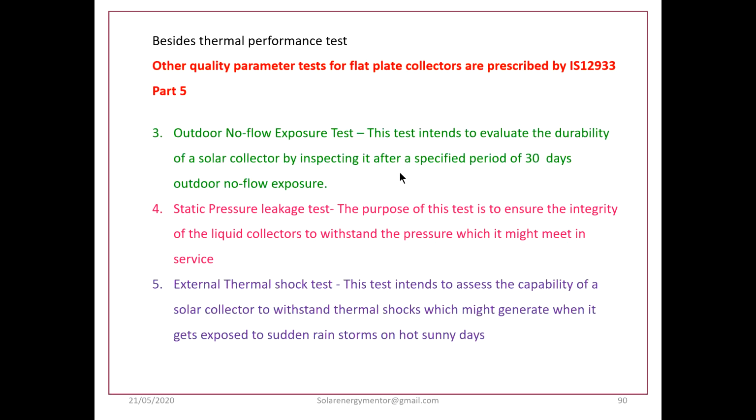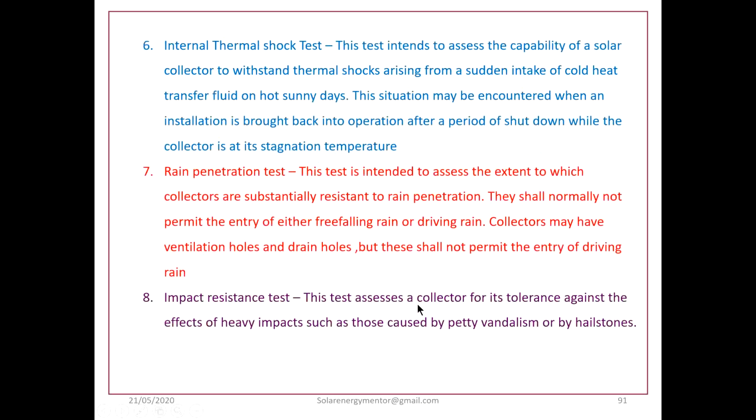Whether it withstands that external thermal shock or not is tested in the simulation or in an actual test platform. Then the next test is the internal thermal shock test. This test intends to assess the capability of a solar collector to withstand thermal shocks arising from sudden intake of cold heat transfer fluid on hot sunny days.